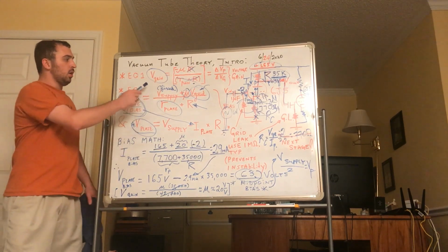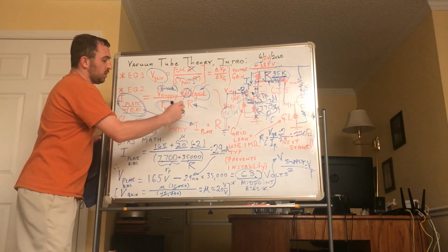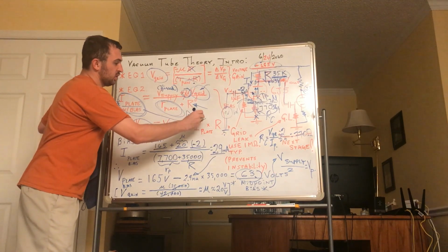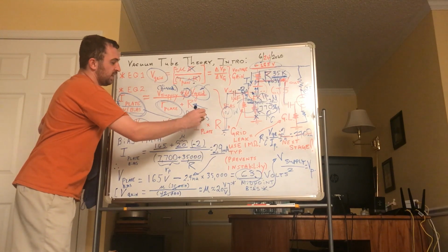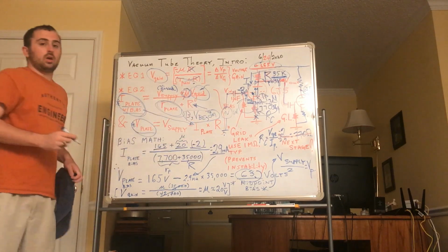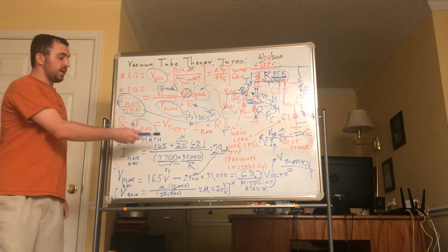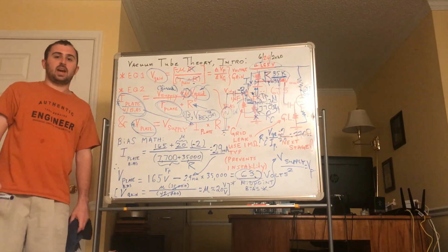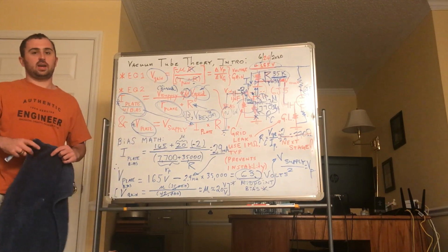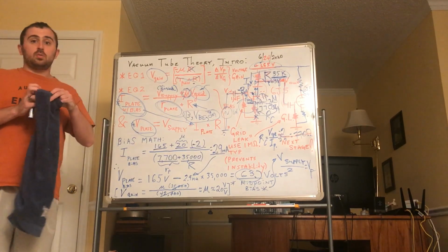They're very similar. The only difference really is that vacuum tubes use mu and RP. Transistors use something called beta. Another quantity of interest would be VBE, which is well known. And in FETs, they have gm. But basically, the equations are very similar to this. So I hope everyone learned something, and that's it for your basic vacuum tube voltage amplifier common cathode theory. This is the most common amplifier when you look at old radios and televisions and guitar amps. And basically, this is vacuum tube theory part 1.